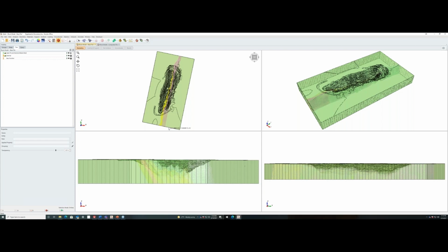Once we have the geometry in, as you know, with our 3D software, we have to do a divide all. So I'm going to do divide all right now. I'll select divide all, and I'll use the default settings. That should take me a little less than a minute. What it's doing is dividing all the geometries so that we'll have several different volumes. When this step is done, sometimes you end up with several small volumes.